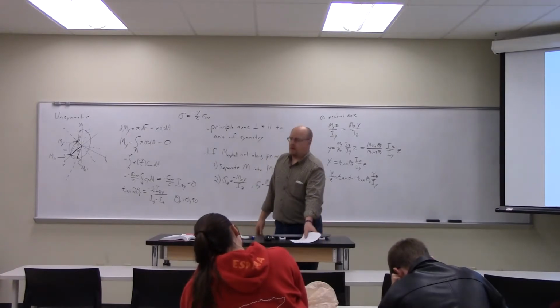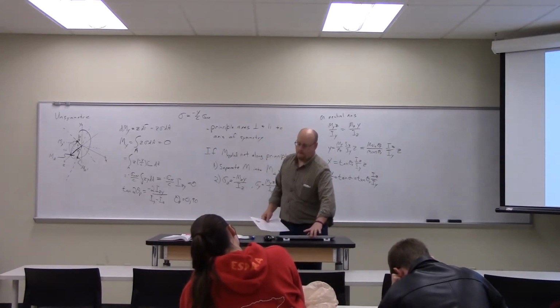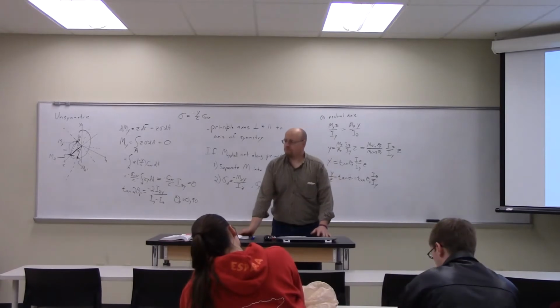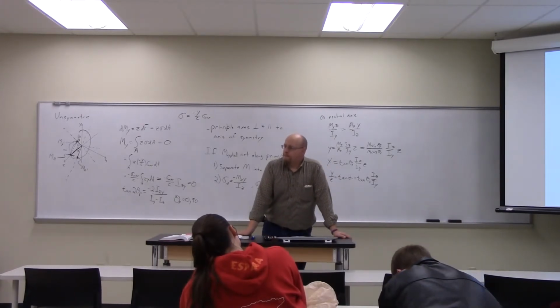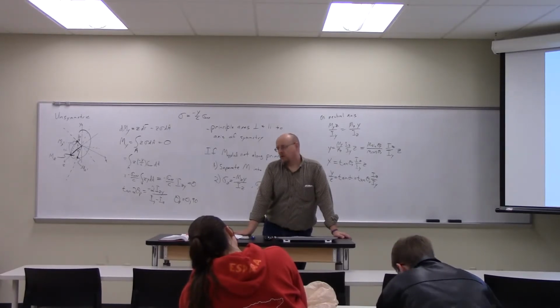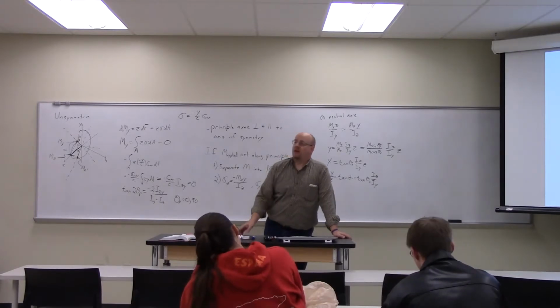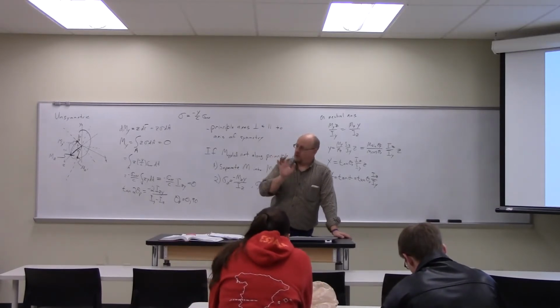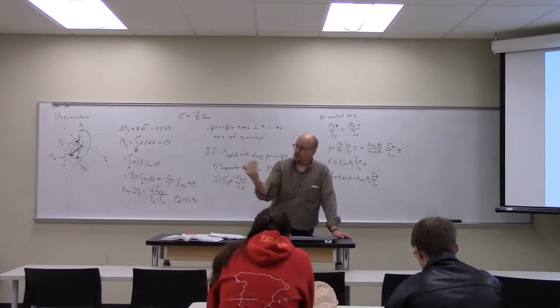If we had a twist on this too, and then we went separately and calculated the twist, we would just add our twist stress into our overall stress. But what kind of a stress does a twist create? Shear stress. So a twist will create a shear stress, a bend creates a normal stress, just like a normal force creates a normal stress, and a shear force creates a shear stress.